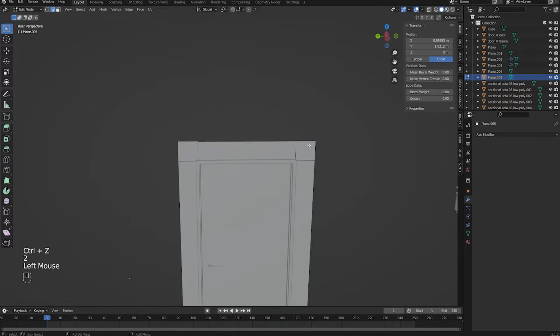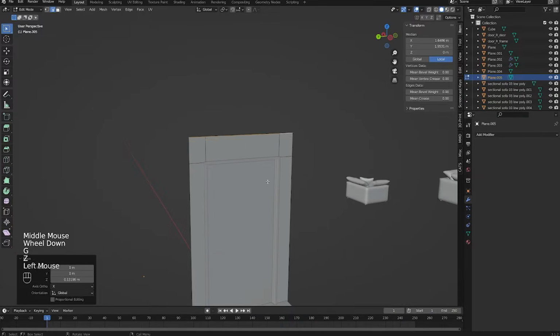So let's go back to edge select. I'm going to select this whole thing. So there's a couple ways I can select all three of these edges. At the top here, I can hold Alt, select one edge, and that's going to give me the entire edge loop of the edge that I had selected. Or I can press one edge and press Control, then select the farthest edge that I want, and it's going to select all the edges in between that are closest. This doesn't just work for edges, this will work for faces and vertices, but we were in the edge select, so that's what we selected. So let's move this up just a little bit.